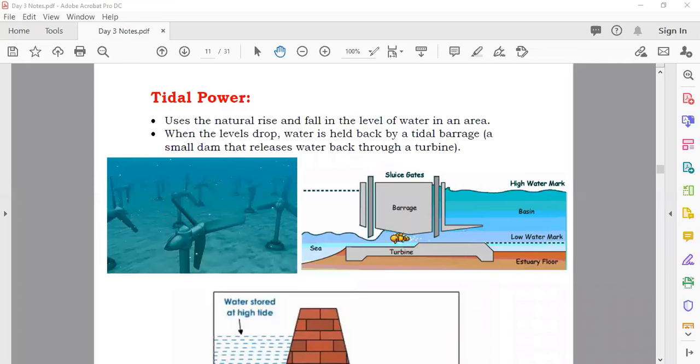Can you explain the last point? Okay. I'm saying that in the day, when the sea tides are low, there is no use. In the night, when the tides become very high, water comes and is stored here. They have a gate here, and when the water comes and it is full, they close this gate. When the gate is closed, the water remains still here. If you open this gate in the night, the water cannot go back because the level here and here is the same.